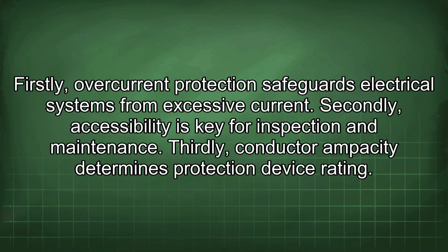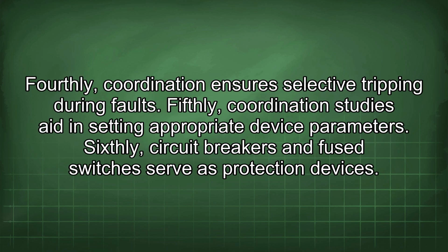Firstly, overcurrent protection safeguards electrical systems from excessive current. Secondly, accessibility is key for inspection and maintenance. Thirdly, conductor ampacity determines protection device rating. Fourthly, coordination ensures selective tripping during faults. Fifthly, coordination studies aid in setting appropriate device parameters.